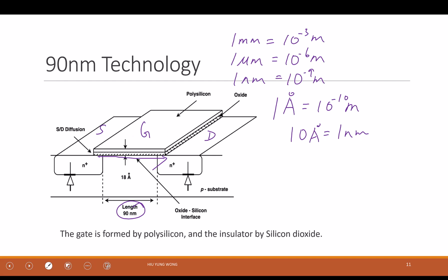Now, in a planar transistor, it's just like you only have one finger to pinch it off in one direction. Now, imagine if the pipe is very wide and your finger is very narrow, it will be difficult to pinch off the current, right? If I have 4 fingers pinching, it will be easier, because when the gate length is much longer, it will have better control.